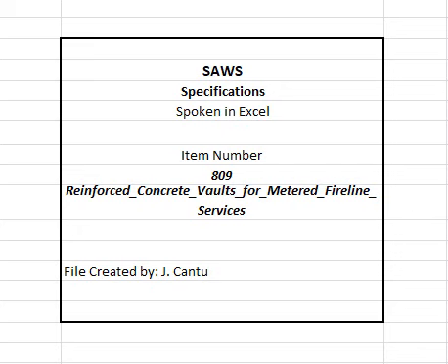2. When required on drawings, submit shop drawings showing reinforcement type, quantity, size, length, location, spacing, bending, splicing, support, fabrication details, and pertinent information. 3. For water stops, submit product information sufficient to indicate compliance with this section, including manufacturer's descriptive literature and specifications.